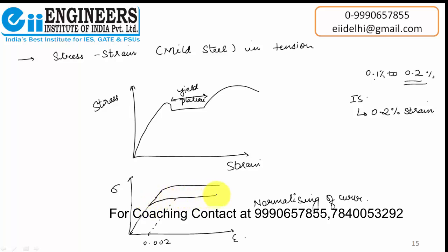Well, before going through this, let me tell you, if the strength of steel is fy, then we apply a factor of safety of 1.15, and it becomes 0.87 times fy. Okay, so now we need to find this strain value. How do we find it? We have already told that we should provide a proof stress of 0.002, sorry, proof strain of 0.002. So this value is 0.002. Now we have to find this value.